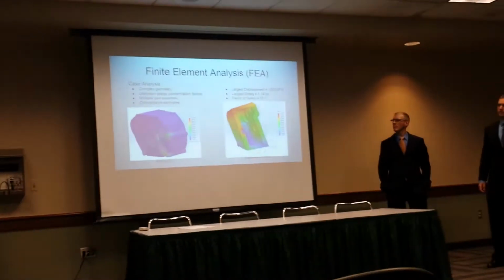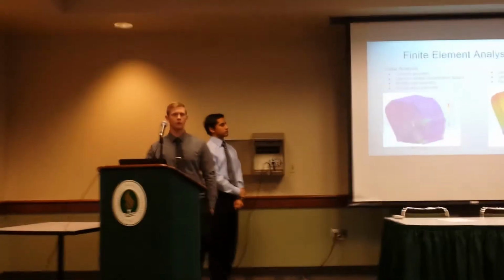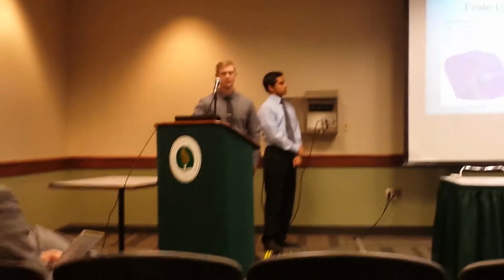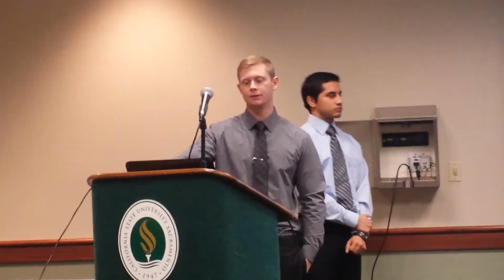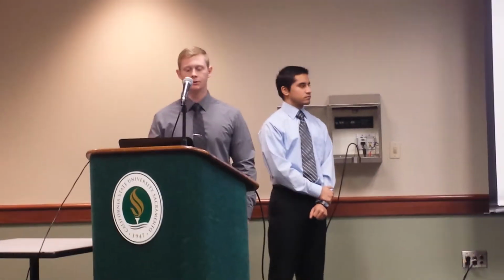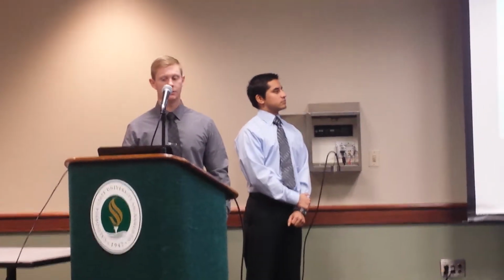Okay, so we used FEA for the more complex components because they have a much more complex geometry as well as unknown stress concentration factors. Also, for the case, it's a multiple part assembly, so it was ideal to use FEA instead of hand calculations.